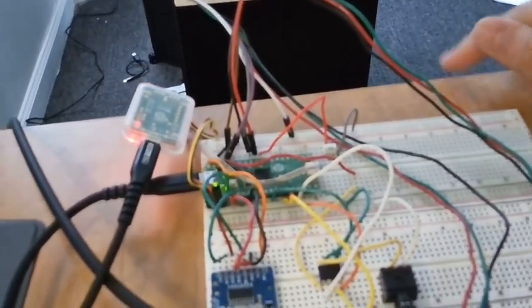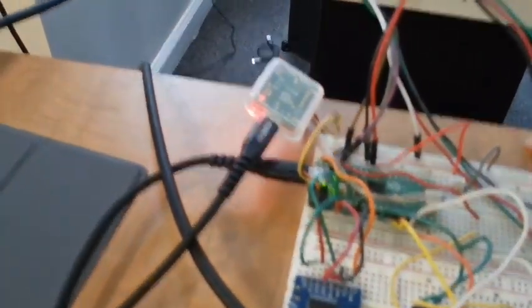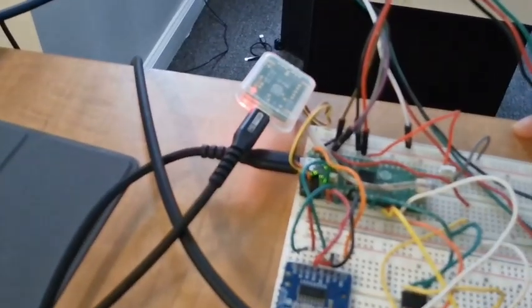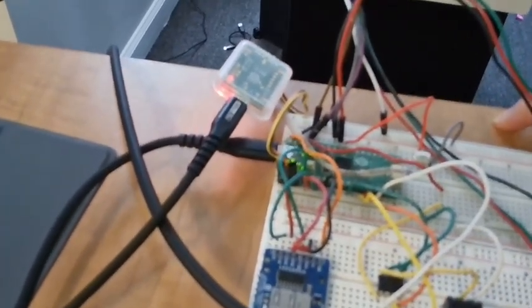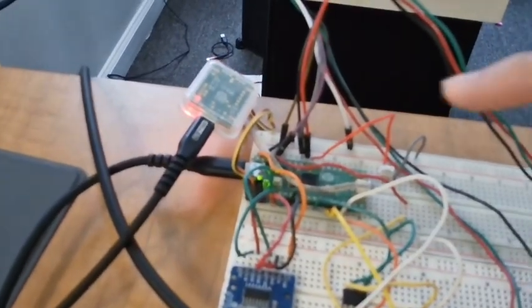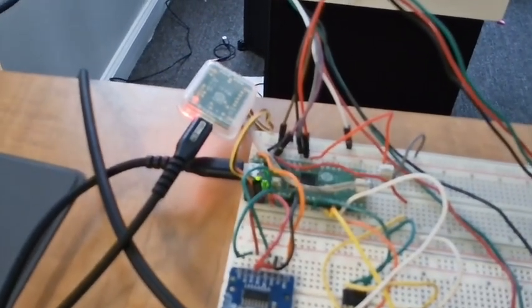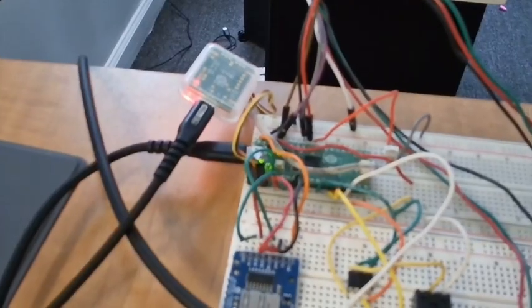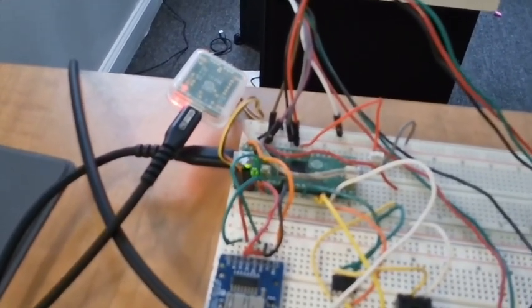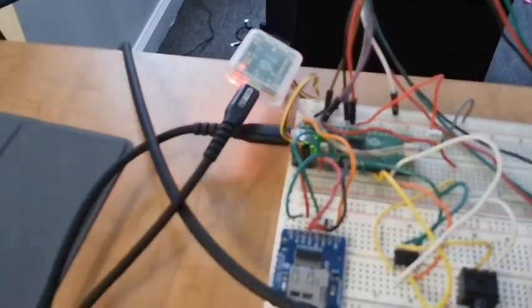Something we realized too late into the project was that all the DSP operations that we did in Python using librosa were by default done in float32, and the DSP library that we use on the RP2040 was the ARM CMSIS DSP library. Although it does support float32 operations, it was not available on the RP2040 because it doesn't have a floating point unit. So given that constraint and the time limit we had, we settled on just doing all the DSP on our laptops.